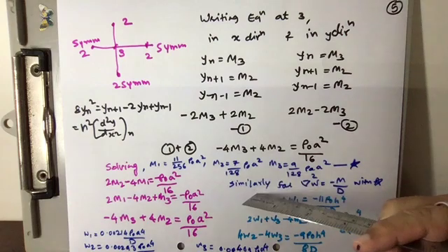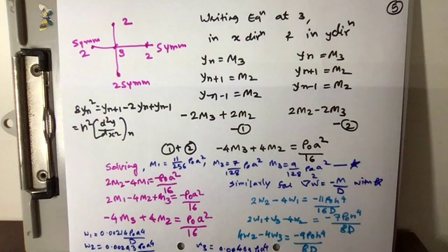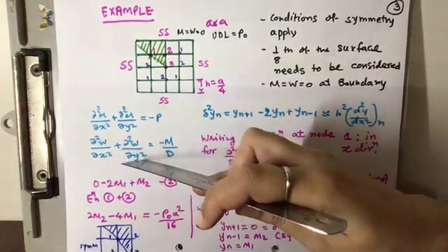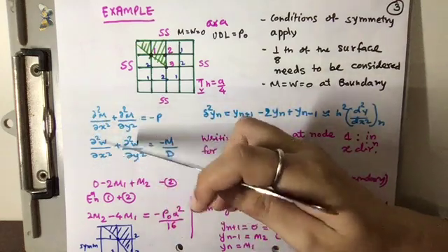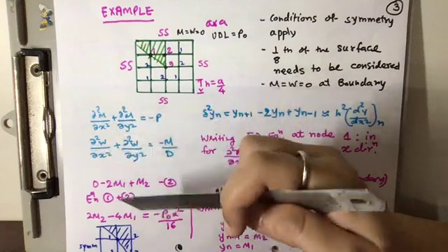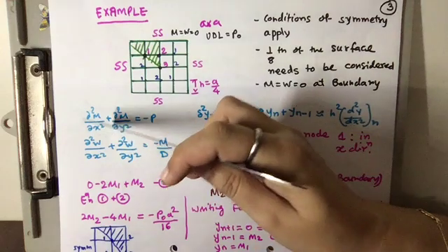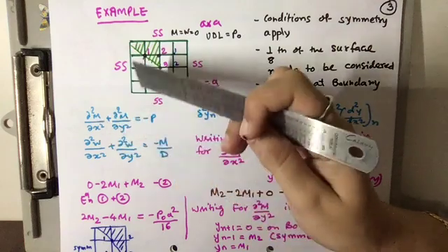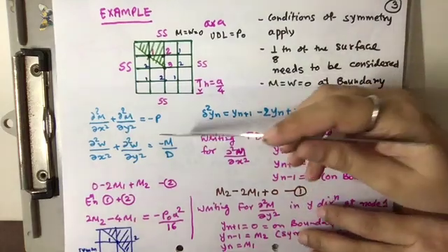Now similar approach we have to follow for the second partial differential equation, that I have shown earlier, which is here. This equation also can be written in a similar way. You can see some similarities here. Both equations are same except the values of m and w. So when you write difference equation at same nodal points, the equation remains same except we are writing w1, w2, w3 instead of m1, m2, m3. So the right hand side is different.